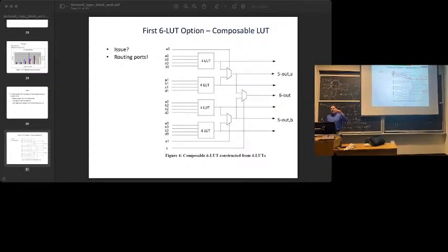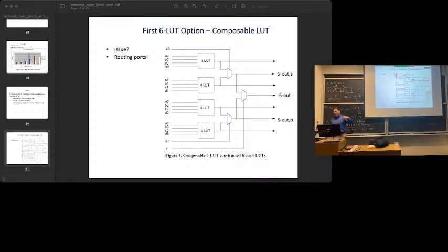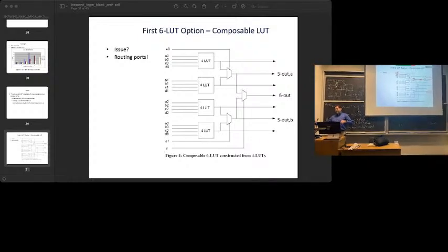Whatever controls the first level of that has the longest delay. Whatever controls the last level has the shortest delay. And actually the CAD tools exploit that. In the routing phase of Quartus, it is routing all your signals, and simultaneously trying to get those signals, if they're critical, to the fastest LUT input. So it's a good observation, but it's kind of just fundamental. It just is always there. Yeah?